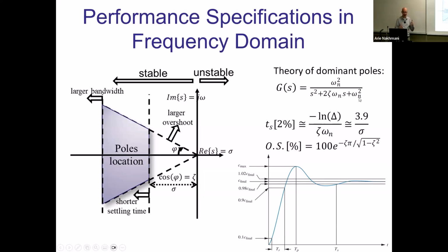So you can use step response of any unknown function to estimate a second order model, which will give you that omega, zeta, and this is all you need to describe the system with two parameters. Okay, because you can measure settling time and overshoot.